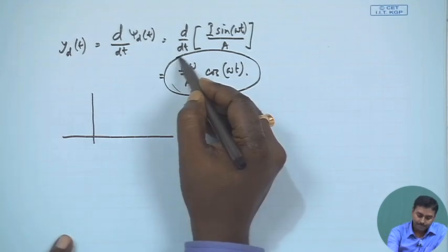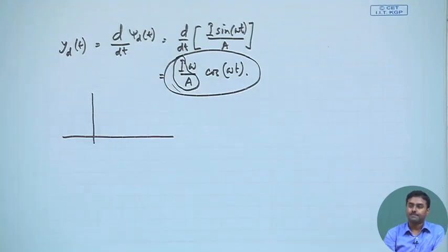First of all, there is a factor of I by A. Okay. We have already said A is bigger than I, so the interference is already becoming A times lesser. So, when it is interfering with FM, because of the FM demodulation process, it is already becoming A times lesser. As long as A is higher, it will be lesser. That is one thing. The second thing is, it is getting multiplied with omega.